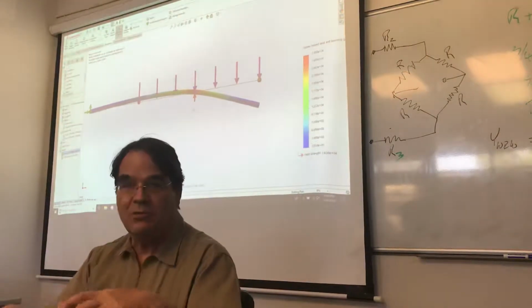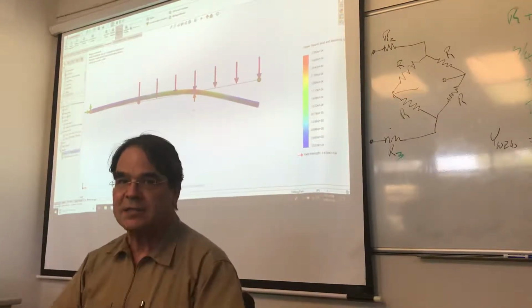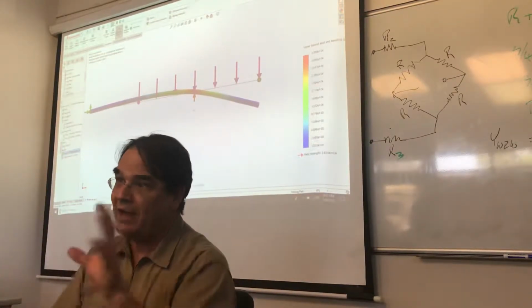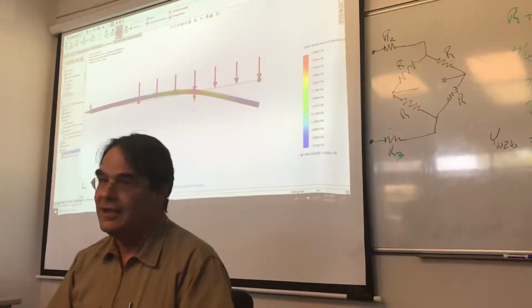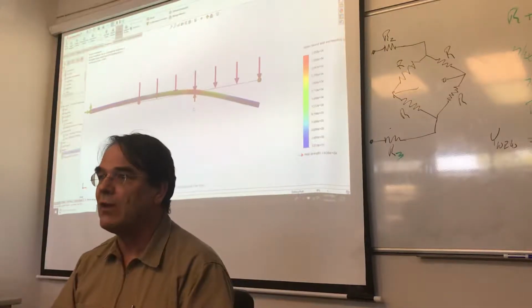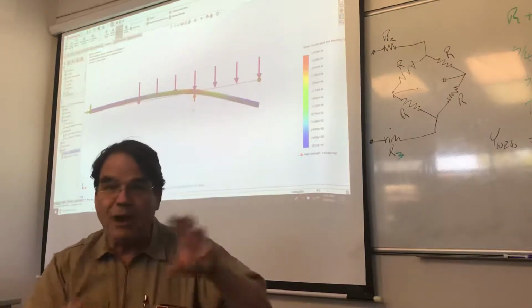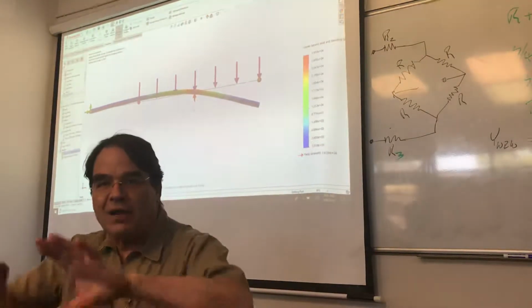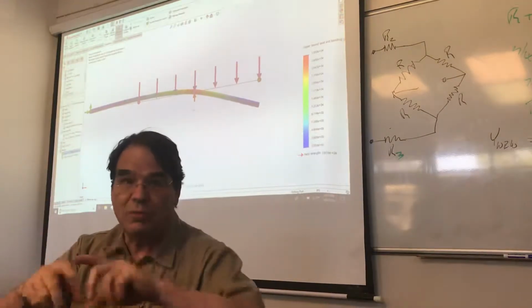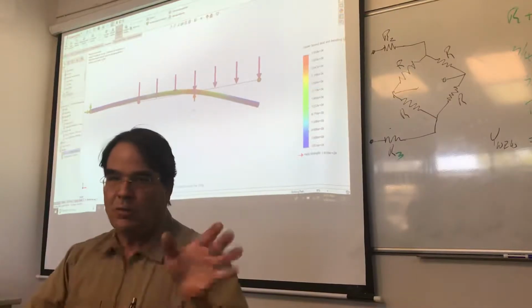It assumes the load magically appears on the centroidal axis, distributed like it's supposed to be. And the fact that, of course, we actually have to fundamentally design things to do that, it doesn't know anything about. So areas where all the beams come together, or areas around the constraints like our supports, it's not accurate around those. Now, it's accurate from what the external loads are doing, but how that load actually gets out of the beam it has no knowledge of at all.